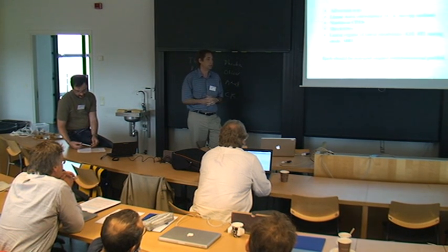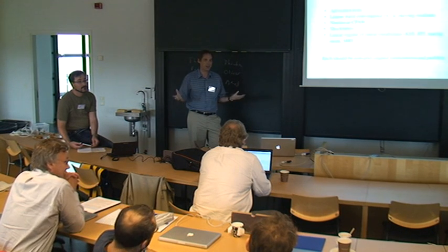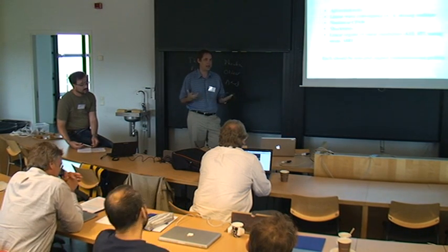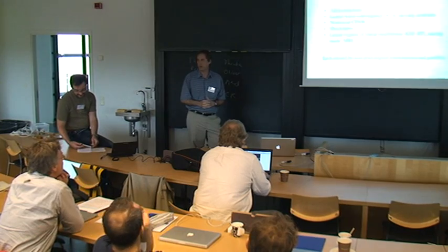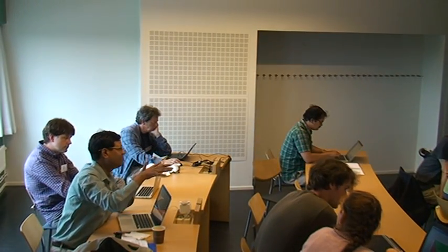Actually, I think that's a fundamental question that everyone here has already answered implicitly by being here. Yes, we think there is, but maybe some reality check on that is what should be discussed. The energy flux for fluids is the Kolmogorov flux, and there's a similar thing for MHD. So we do a simulation at, let's say, 1000 cubed and at 256 cubed, and the flux must match for whatever wavenumber range is available to us. I think that is the most stringent test for LES or for low resolution simulation.